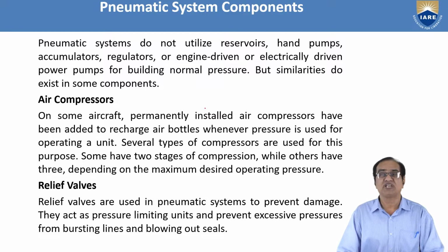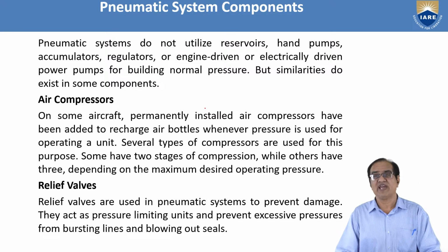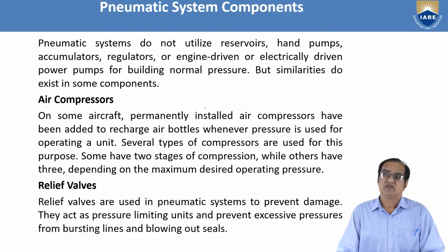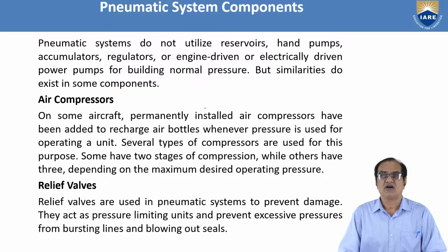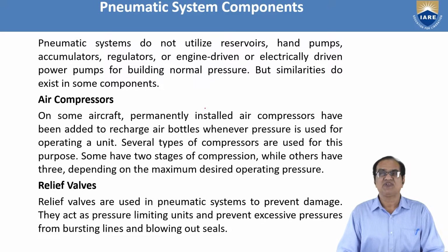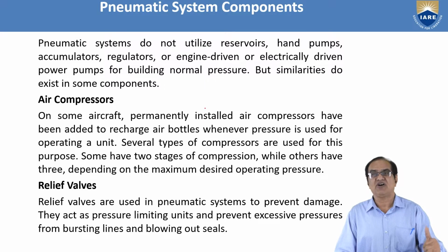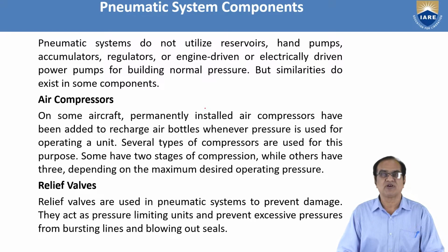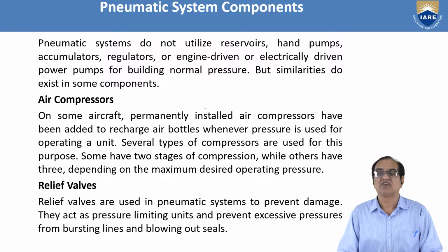Second thing, we have the relief valve. This relief valve acts as a safety measure. As and when the pressure of the air is increased to a given value, there is a spring loaded valve. That valve will open up and the excess amount of pressure which is acting on the system will be relieved to the atmosphere, and the pipelines and all the equipment will be safe.